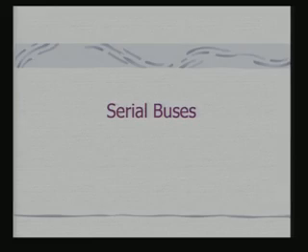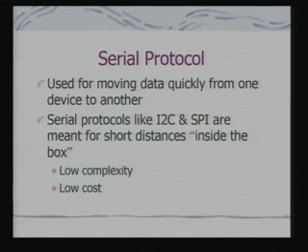Next, we shall look at serial buses. In fact, when we looked at this SOC and PCB based application, this whole concept of the buses had been parallel data transfers. If we are transferring 32 bits, I shall be transferring that on parallel lines. Obviously, this can be used for short distances, within a chip or within a card. The serial buses that we are now talking about are also for short distances, not really very large, and the basic idea is for moving data quickly from one device to another.